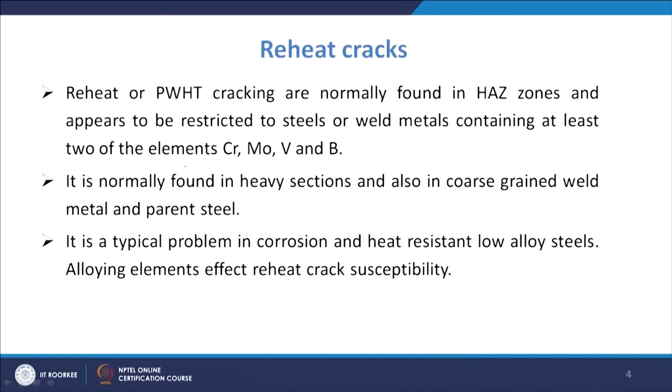Reheat or post weld heat treatment cracking is normally found in HAZ zones and appears to be restricted to steels or weld metals containing at least two of the elements chromium, molybdenum, vanadium, and boron.